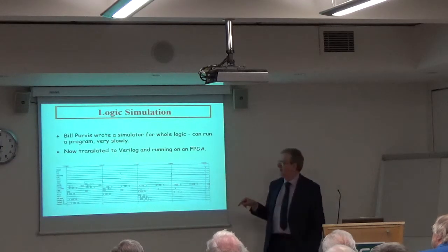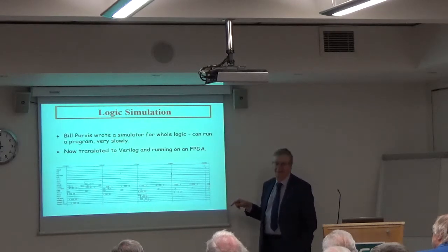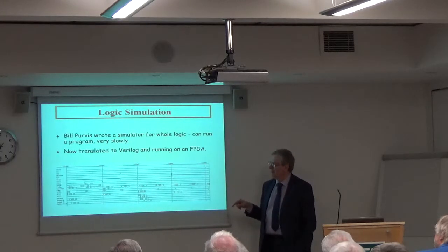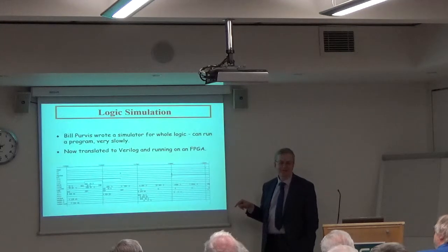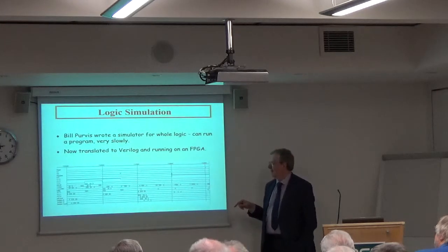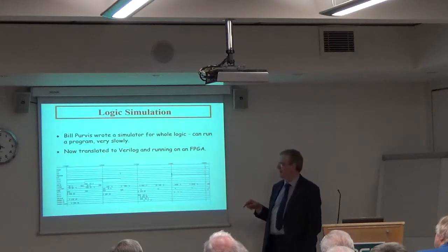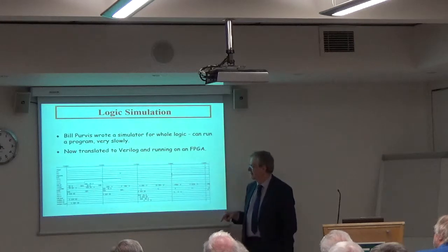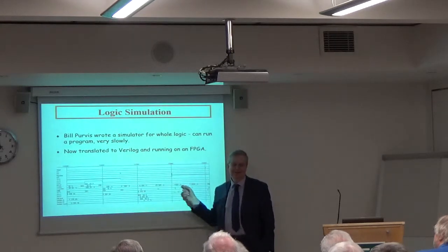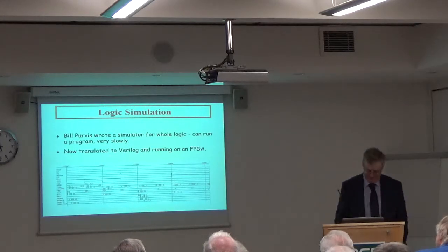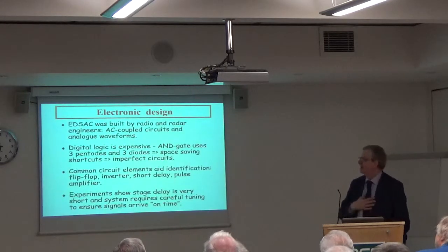To make a long story very short, it was clear the EDSAC pioneers weren't bothered about noise in the way that modern digital engineers are. They weren't particularly bothered about what levels were, providing they were different, and pulses didn't have to be very square. It depended whether you wanted an edge or a level as to how hard they were trying to clean things up. So if you're looking at EDSAC on an oscilloscope, you never see anything as pretty as that. It's all much spongier and fluffier and wobbly. But there you go. So that takes us to electronics.